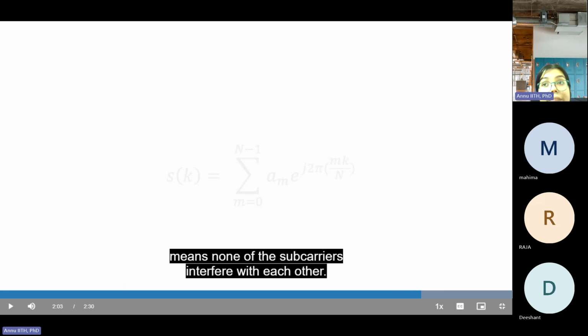Okay, now when we have modulated symbols, they will be modulated with respect to the carrier frequency e^(j2πmk/N), where mk/N is the frequency of each subcarrier, and they differ by m. Like 15 kilohertz is the frequency of one subcarrier, then a multiple of the first subcarrier will be the second frequency. So 15 into 2 will be 30 kilohertz, 15 into 3 will be 45 kilohertz. So with integer multiplications, these subcarrier frequencies vary. Once they are summed, then they are sent.